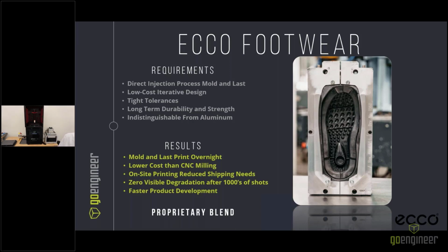This is a proprietary blend of material specific for their use case. One thing that I would like to touch on here is just because the stated HDT of a material might be lower than the plastic that you're injecting into, does not mean that you can't use it. There have been a handful of other proven use cases where the HDT is lower than the urethane or plastic being shot into it.